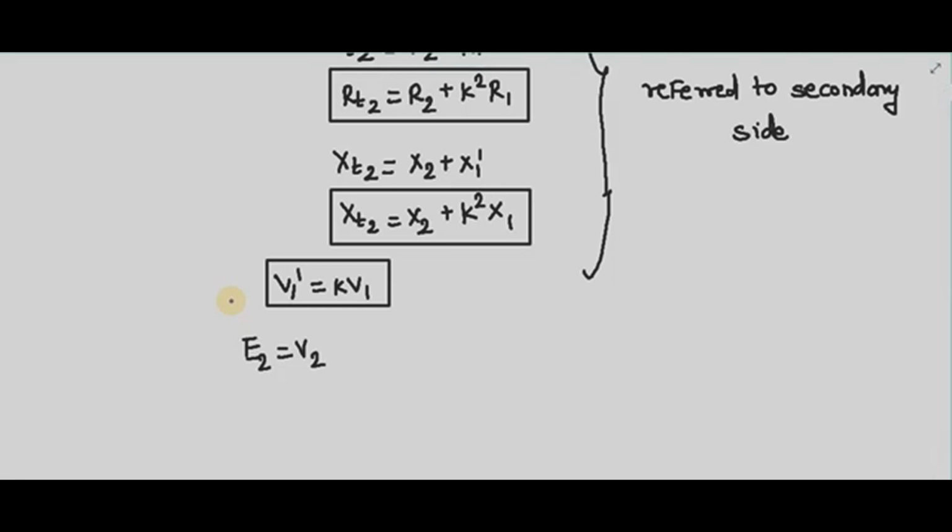every winding has some resistance and reactance, and a drop takes place in those resistances and reactances. So when no load is connected across the transformer, the mutually induced EMF across the secondary is equal to the terminal voltage V2. But once I connect the load, with increase in the current delivered, the resistance and leakage reactance drops of the primary winding cause a decrease in the value of the primary induced EMF E1.